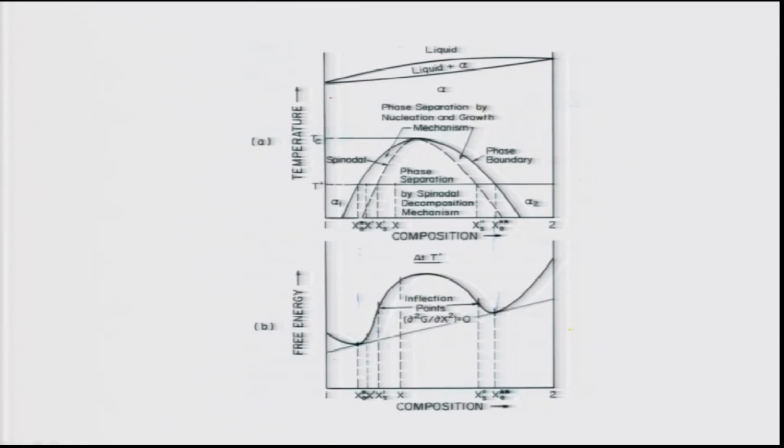isomorphous type phase diagram, leading to formation of the solid solution alpha. At temperatures above Tc, the alpha is stable, it is a random solution. At temperatures below Tc, it undergoes spinodal decomposition, and everything is shown here. The inside curve is known as the chemical spinodal, because that is where the transformation will happen via spontaneous decomposition, with no need of nucleation.